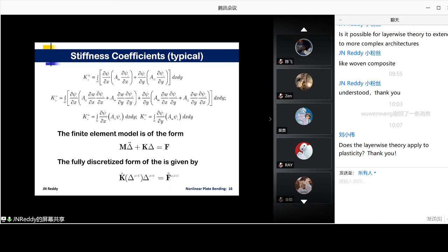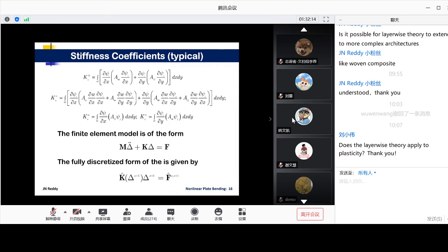Whereas other schemes which are conditionally stable, you are required to obey the requirement of stability, which usually poses a restriction on the time step size as well as on the mesh. So that means if you pick a mesh, it dictates a time step. And if you refine the mesh, your time step will go down. That means a refined mesh will automatically not be stable. It gets worse, actually, until you make your time step even smaller. Okay, because that is the relationship in the stability criterion.